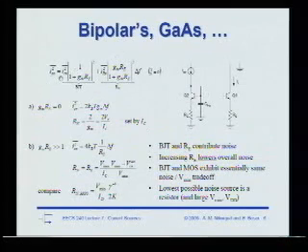If you look at this expression, remember we just did this calculation. We found that the noise of this transistor is rejected by 1 plus Gm RE. That's the expression we just calculated for the cascode, where RE now is a physical resistor instead of a transistor. So this resistor is rejecting the thermal noise of this device. That's great, but it's also injecting its own noise, right? So this is the total noise.